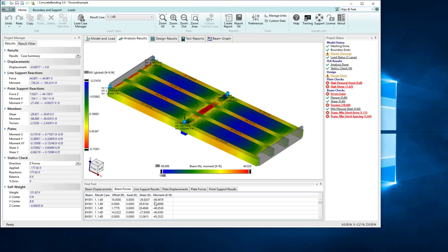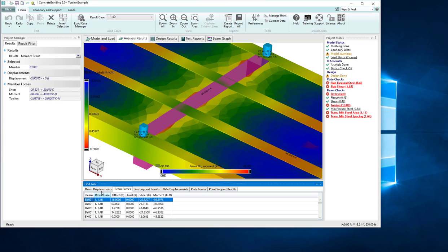And now we're showing negative moments going from minus 98 all the way up to a positive moment. Let's go back to the negative 98 moment, scrolling to that part of the list, and I'm going to double click on this row. Now we zoom in on the beam that this moment applies to. So very powerful to locate result values graphically by double clicking in the Find tool.